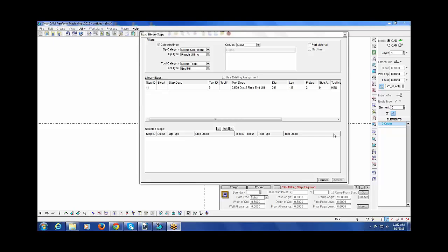One thing, if I may jump in here, that's important is when we have a process, you should not underestimate that there could be 2 or 3 tools daisy-chained, or sometimes 20 tools to one process if you do port machining, or like a center drill, a drill, and a tap. So it sure would be nice if you look for an M8 tapped hole, for instance, that you can pull in all associated steps and tools. Okay, yeah, I think we have that covered, but you'll have to tell me when I show it to you. Anybody else?